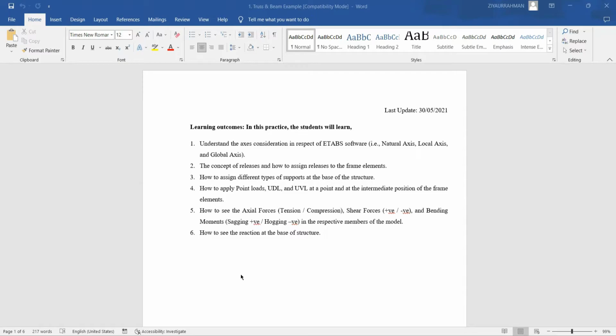The joints are assumed to be perfectly smooth, no friction. Okay. Yes. The joints are perfectly pinned or hinged. Another student also said moment transfer is not there, so both things are the same. If the joint is hinged, the moment cannot transfer. If the joint is hinged, only the axial force is going to be transferred.